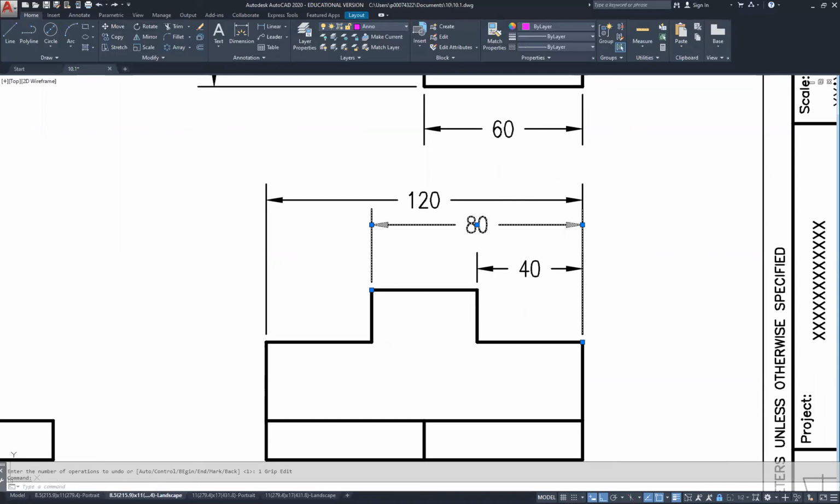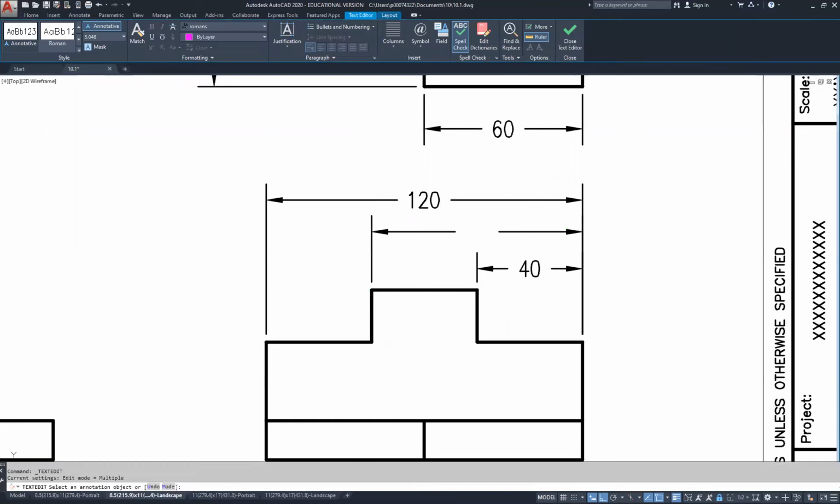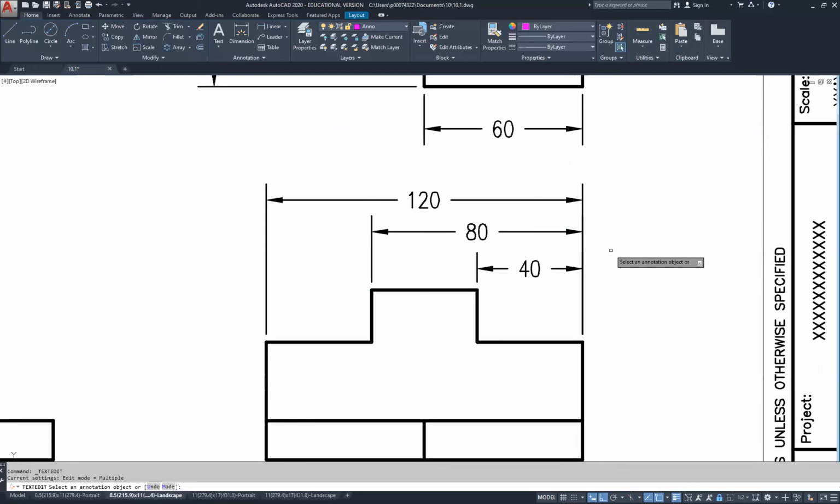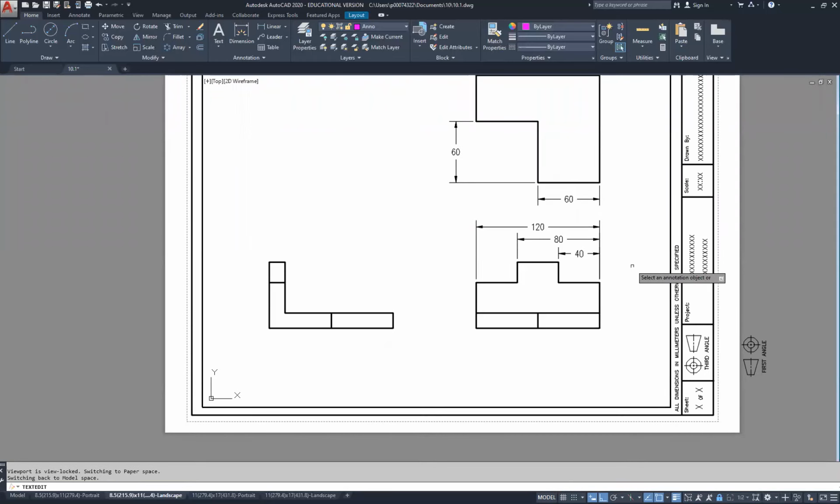Click away from the text. Let's hit escape. Select this. If I move the text from left to right, it could change the alignment of the text. I may not want to do that. For this case, I could also grab the arrows here and using my nearest snap to any point along that line. Hit escape. I was trying to adjust my text. Something I want to do.